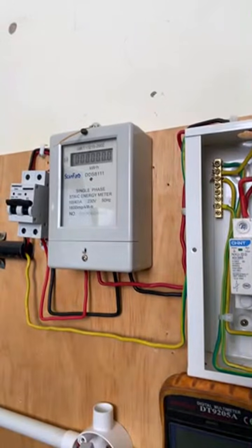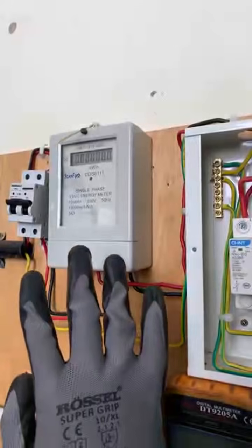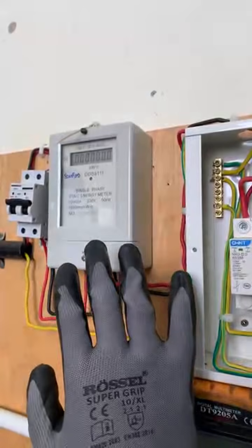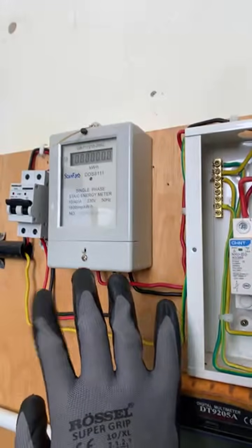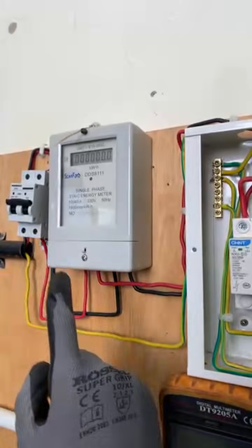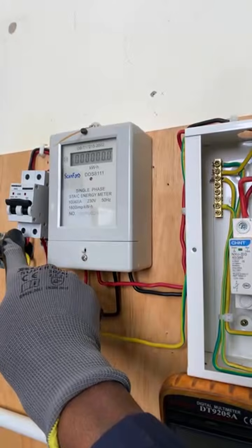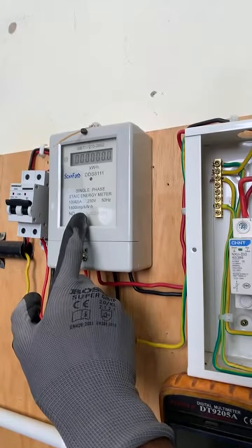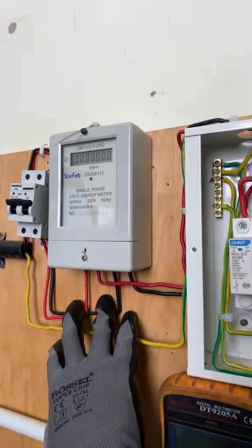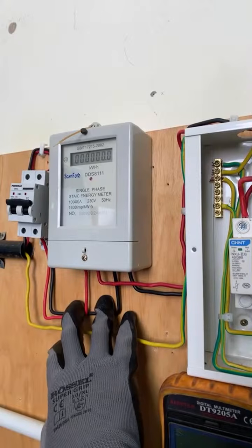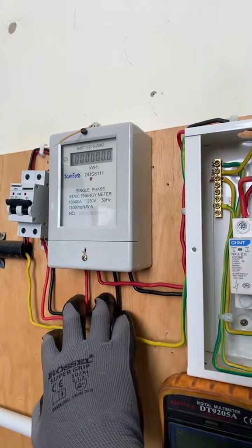If a customer ever calls you and tells you that they had an issue whereby there was burning of bulbs, TVs, and the lights, and the neighbors are not affected, that is an internal fault, a localized issue. Mostly, it is a loose neutral. If the neutral is loose, it will lead to a surge. And that is normally what we locally refer to as a return, a loose connection on the neutral.